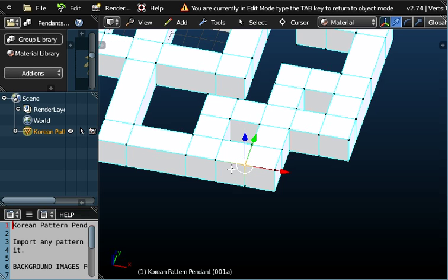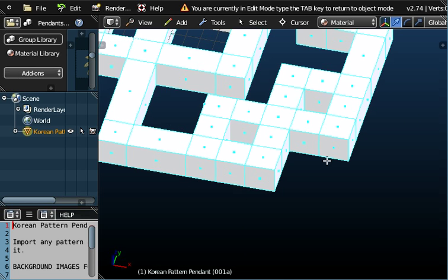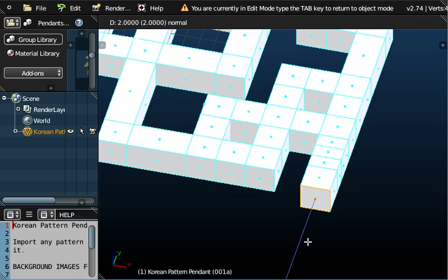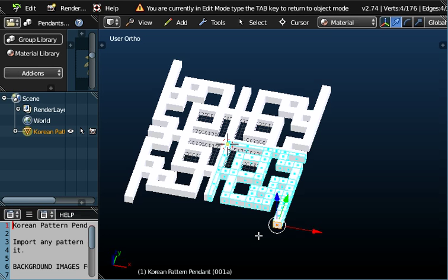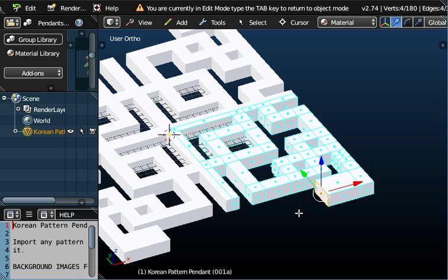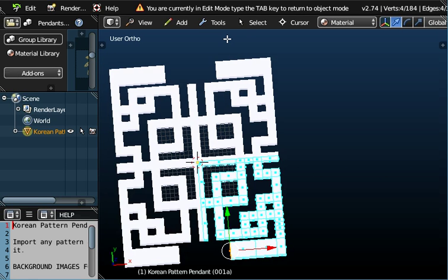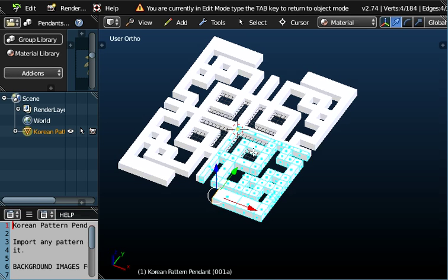Here we're working with the vertices, but if I click the right mouse button we can work with faces, and this is actually much more powerful, because if I click on a face here, what we can do is expand it outwards, and as I expand that outwards I'm actually changing the object in the other four corners as well. And so this is how the pattern has been built up, by extruding it, by extracting it outwards to create my object. And so starting off with a simple cube, you can generate complex objects and beautiful designs.